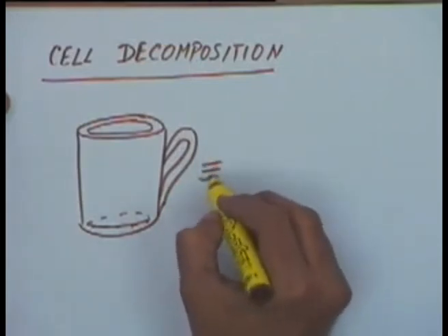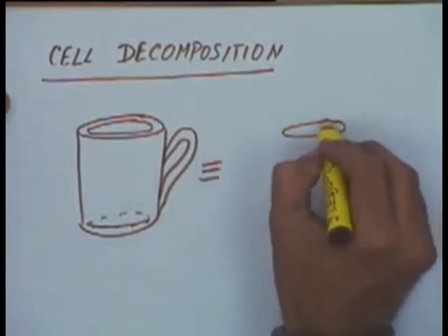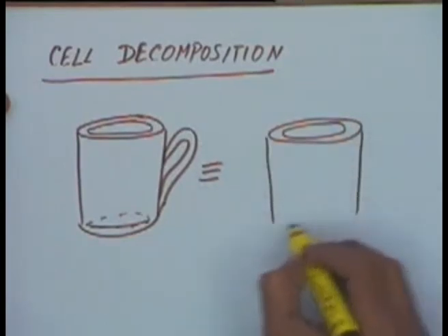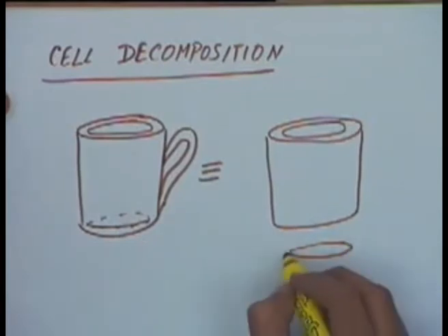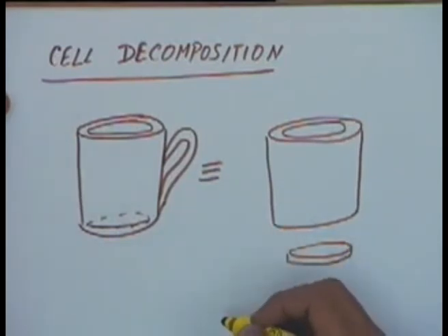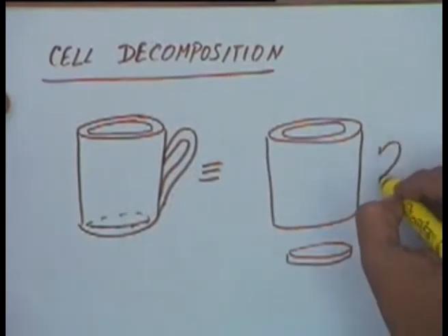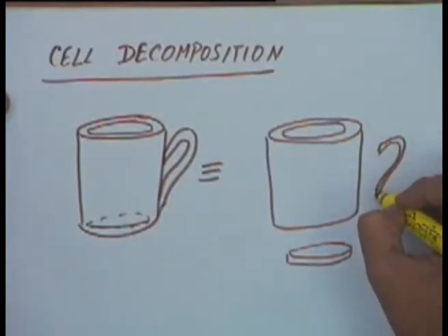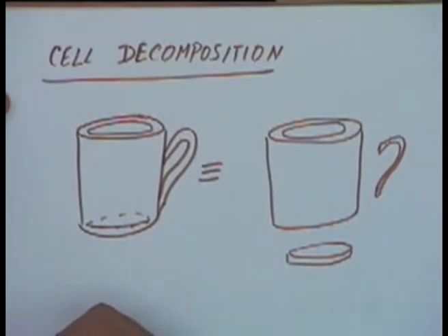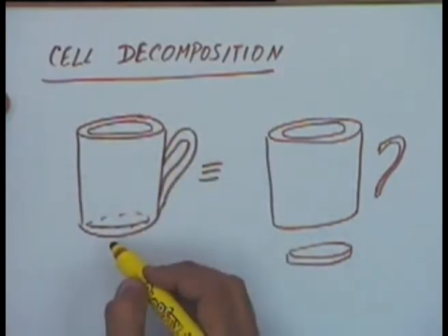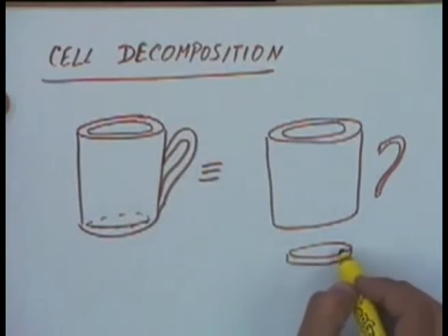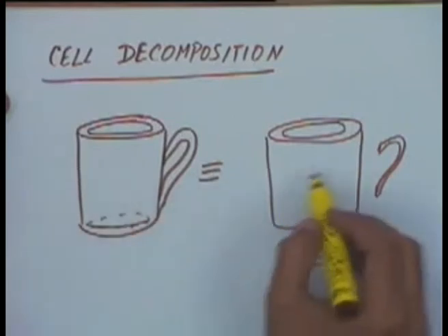This solid, I can represent by one simple hollow cylinder, its union with a disc, and its union with this handle. So what I am effectively doing is taking a solid like this and decomposing it into 3 different parts. Each of these parts can now be represented relatively easily. And I'll say this solid is the union of these 3 parts.